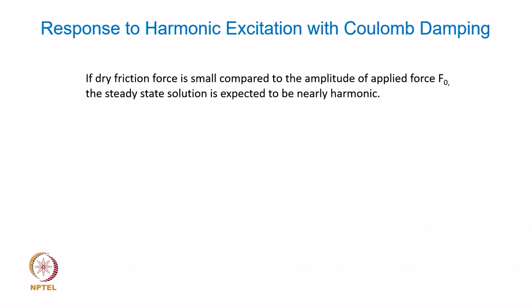But as we know and discussed, in case of a free vibration response to dry friction damping or Coulomb damping, the governing equations themselves are not linear, because the sign of the dissipating force keeps flipping during a single oscillation cycle.